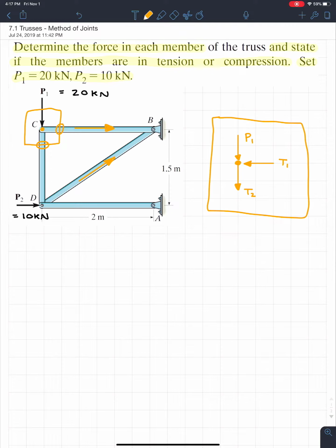So now we have to ask ourselves, okay, well, we have a problem. I don't know if it's in tension or compression. Sure, you guys can look at the structure, and based on the loads, you can probably make a pretty educated guess. But we don't know. So it kind of goes back to support conditions. We definitely remember support conditions, but we don't know which direction the forces are going. If I had a roller, I don't know if the force is going to be pointed up or pointed down. So now we're going to have to go back to something which I know all of you guys love so much, and it's going to become such an important part of all your careers, and that is called assuming.